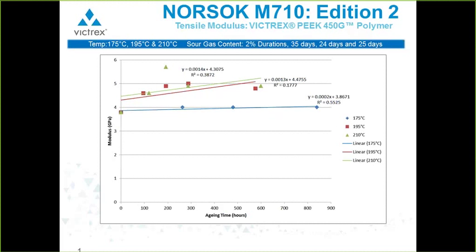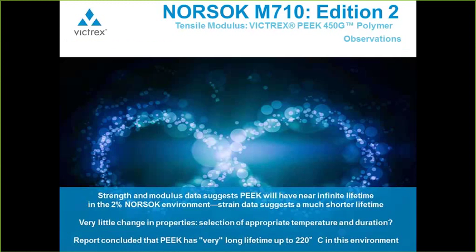And on this basis, I would suggest, and we'll come back to this, that modulus as a criterion for applying this test to thermoplastics is probably not a good choice of parameter to use. This is very much a useful property when considering the performance of elastomers, but I think there has been a considerable amount of carryover from one industry to the other.